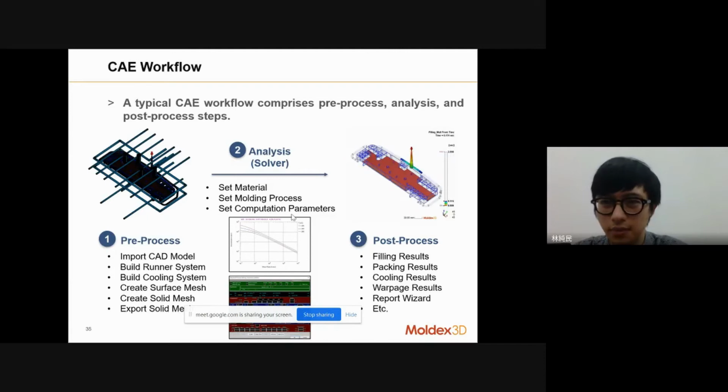So at first, the speed can be very fast, but in the end, this concept is similar to the VP switch, because in the end, the cavity is already going to be filled. So you don't need to use 100% speed to fill in the melted plastic.